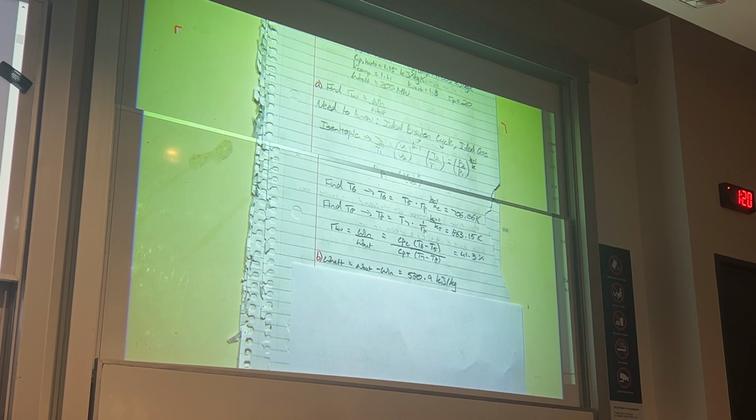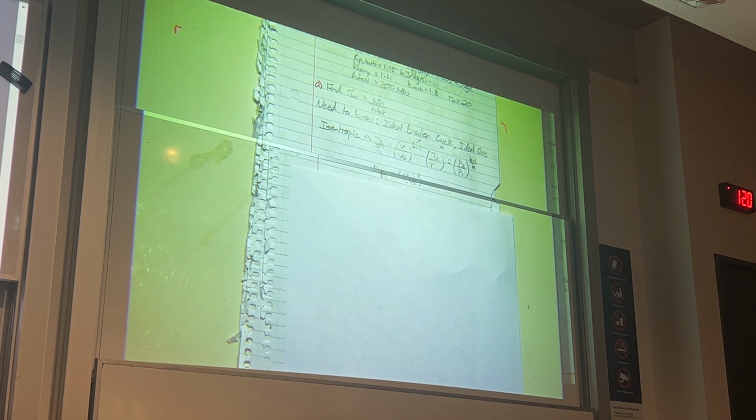So we're given the net work, yes. Sorry, just going back to that, how did you go from your ideal gas rearranging the isentropic assumption to get the RP term in those equations for T6 and T8? It's given, so we're given RP equals 20. So we enter the compressor at 1 atmosphere and we exit at 20 atmospheres. And then because we have isobaric heat addition and heat rejection, we must come back down to the 1 atmosphere. So that's why across our turbine it's 1/20.